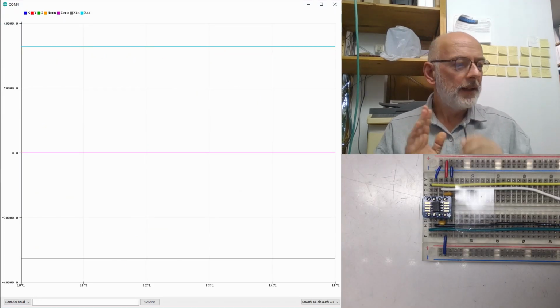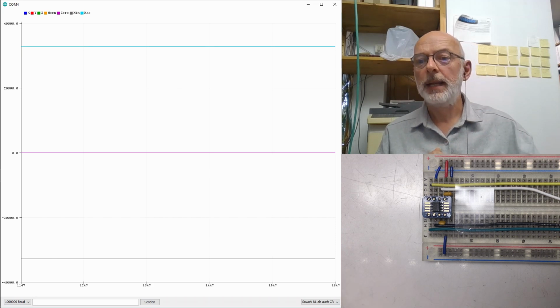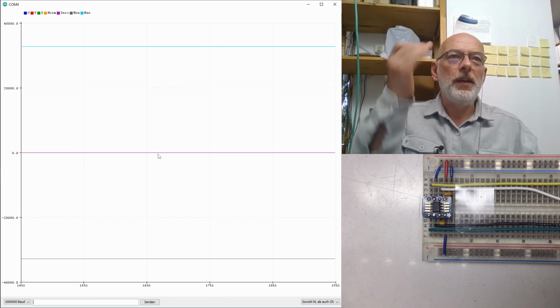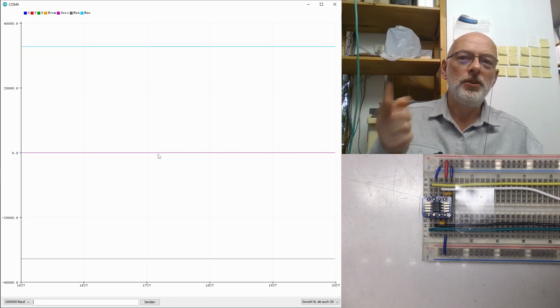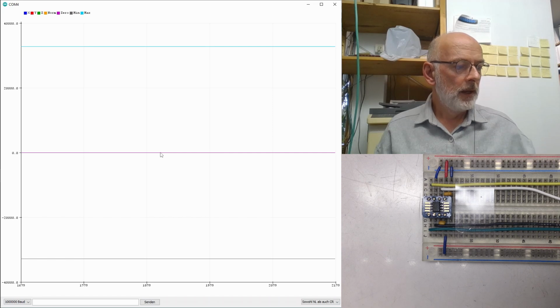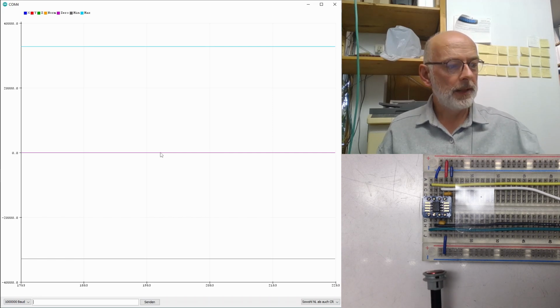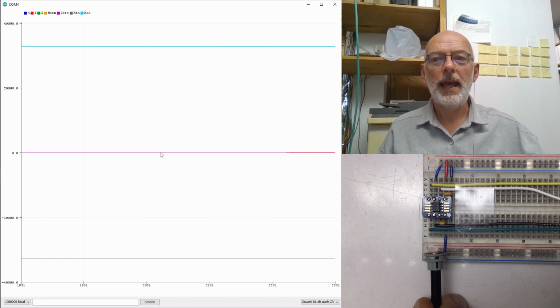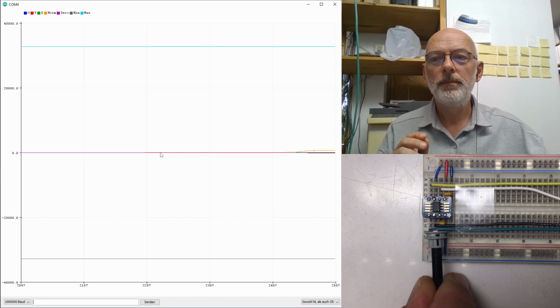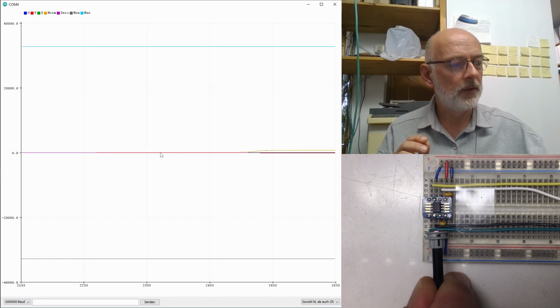Okay, what we can see here with the magnet still in my hand, we have a lot less noise on the data. And we are measuring stuff. That's because the amplification after the analog to digital conversion is now fixed to 0. At least it should be. So if I'm here at the very edge, you might see a little bit, not much. Let's go closer. Yeah, we're getting a signal.